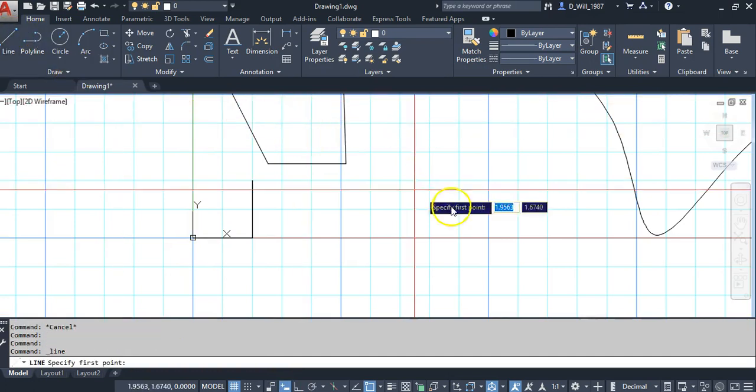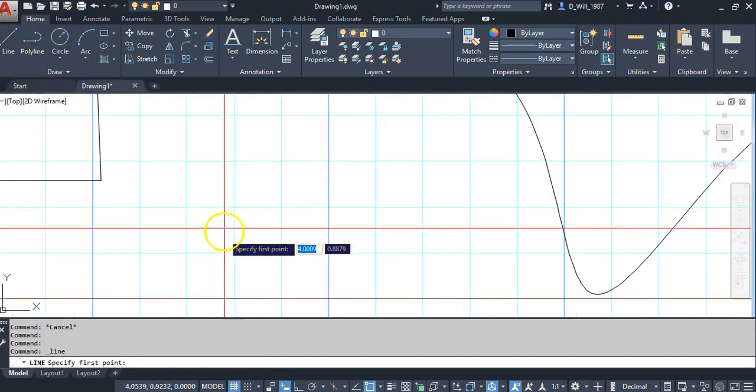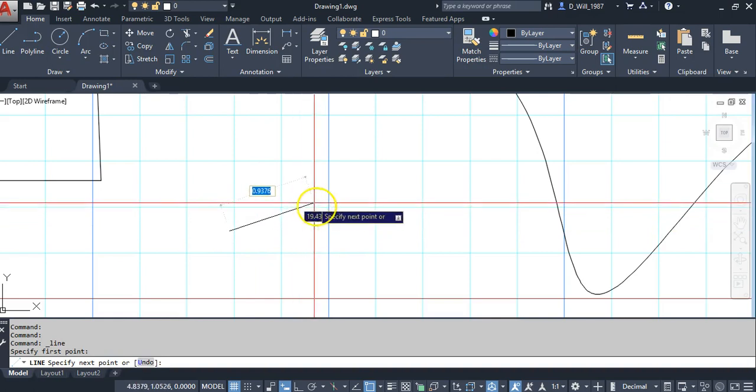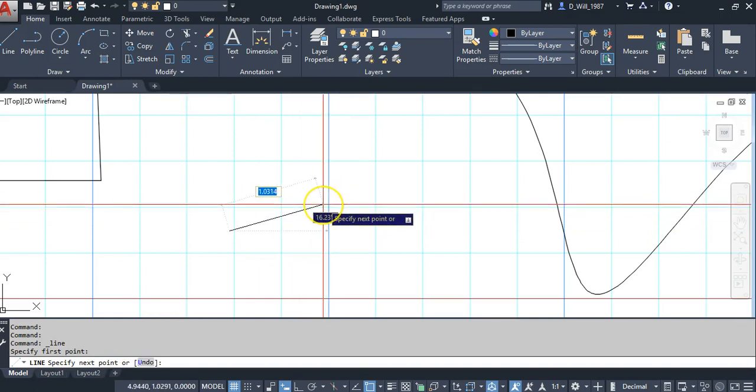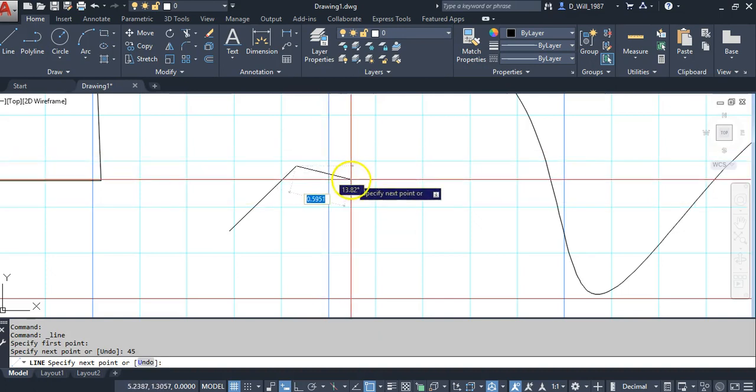The correct way to work with it, if you haven't used it much in the past, is once you start drawing, you see how the box for the length is in blue? Well, if you type a number, like 1, see that number just appeared in the box. And then if you hit Tab, well, that goes to the next box, which has the angle. And if you type into there and hit Enter, you'll get your 1 inch long, 45-degree angle.